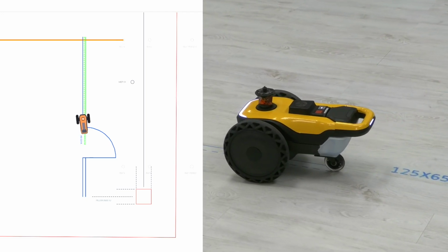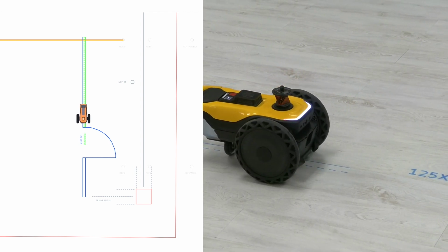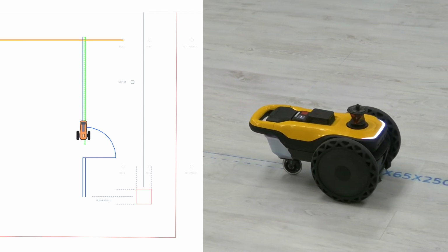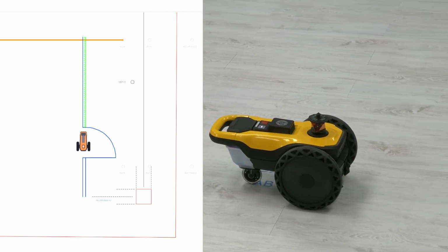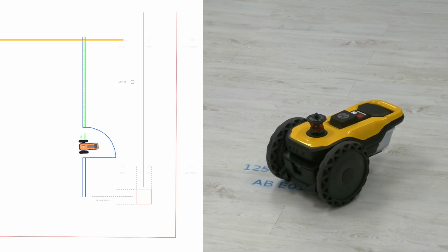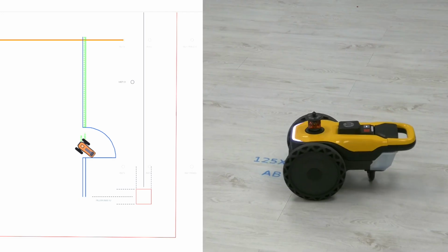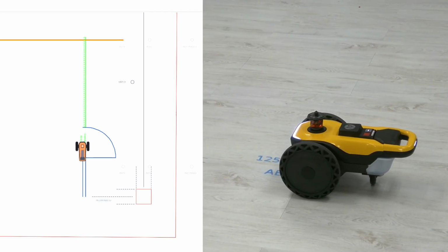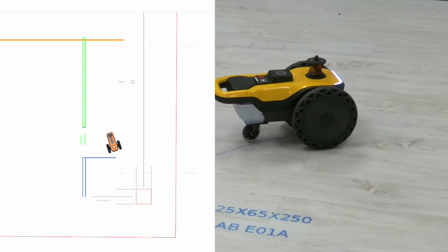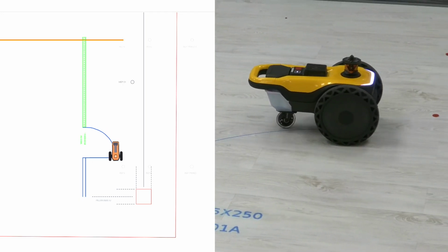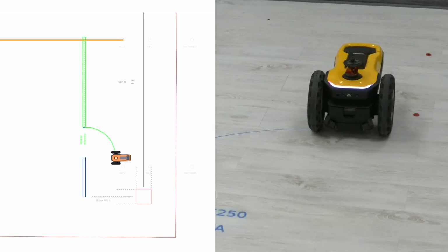HP SitePrint can also print text up to 2 inches thick directly onto the surface. This means that you can provide additional information to the job site that will help reduce errors by the operators who will come later to execute construction tasks. In this case, we will print information related to the door model that has to be placed in the space and the size of it. It can also print complex elements like dashed lines, arcs, or circles. This enables the possibility to mark additional information on the surface other than the traditional lines printed with a chalk line.